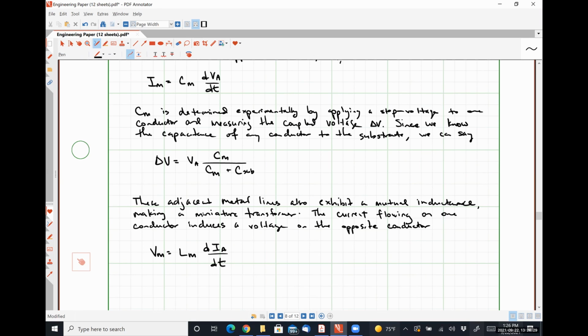You could make them orthogonal, but that's not the obvious answer I'm looking for. Yeah, make them further apart, which is exactly why we have design rules saying the minimum spacing between the wires has to be a certain thing. That minimum spacing rule is there to minimize crosstalk.